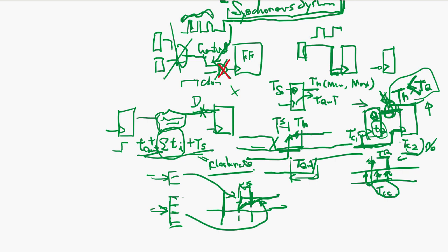So that's why clock distribution has to be designed separately for the entire chip. How many flip-flops in this module, and the clock has to be generated for each module, and if within the module there are too many flip-flops, it has to be divided. And if you have extra delay here, every clock needs to have an extra delay.